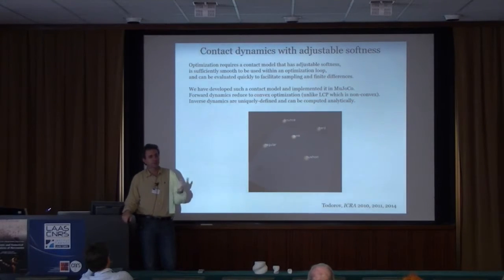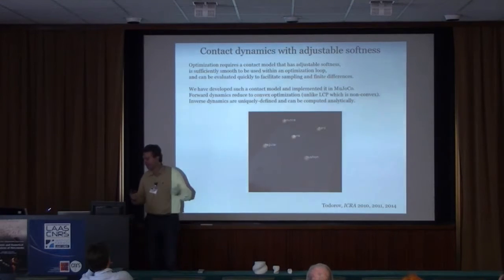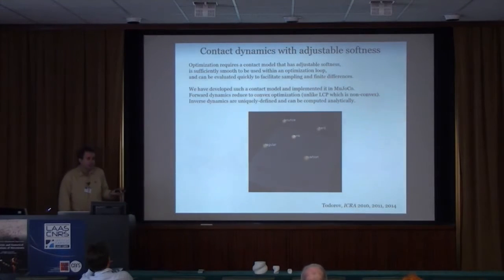So what we're trying to do is tweak the laws of motion of rigid body systems to capture phenomenologically the underlying non-rigid phenomenon. Whenever you try to do that, you're obviously doing all kinds of approximations that are all bad in some way, but some are worse than others. So that's why this research field is actually still open. It's a fairly active literature on developing contact models of the physics of contact.